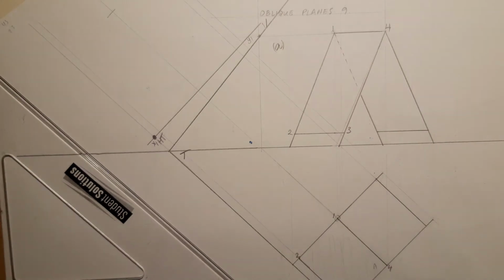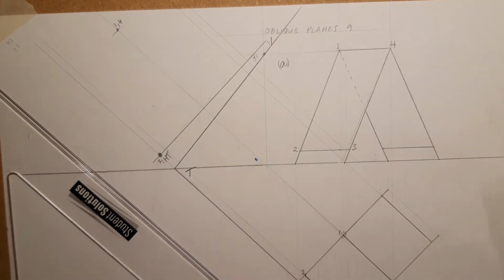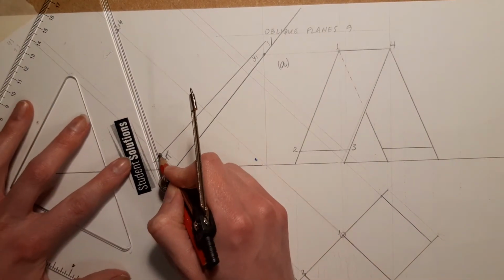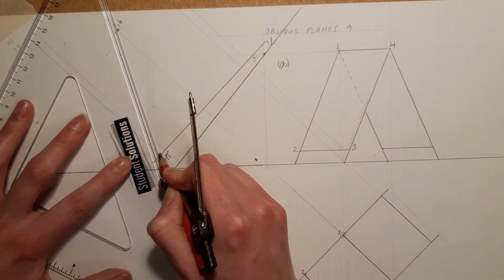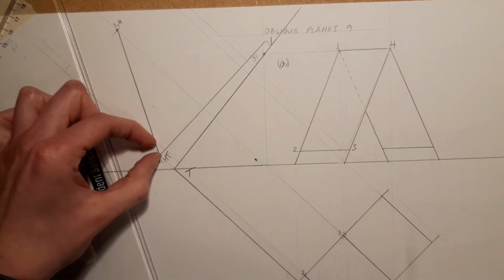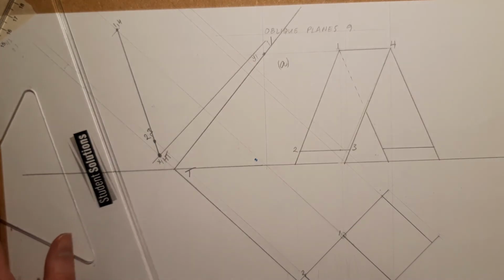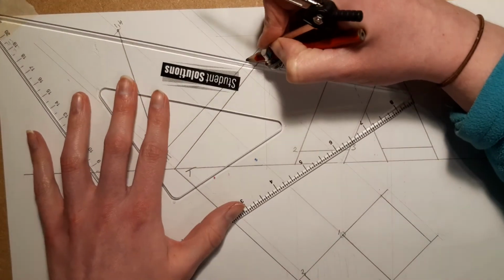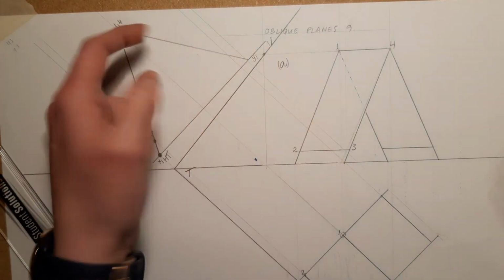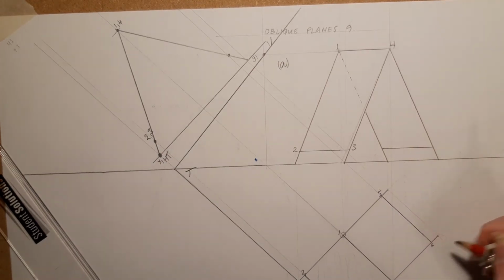So you can see out there now, I'm after finding the point 1 and 4. I haven't found 2 yet, but I will in just 2 seconds. If I join the corner at the bottom of the sandwich board to the top of the sandwich board, okay, that's the sloping surface. The leg is this long, so this point here is 2 and 3. And as I was saying to you, this is a triangular board. You see them outside shops loads of times. Okay, so that is the triangle. That's the other oblique plane. And I'm going to call this 5, 6.